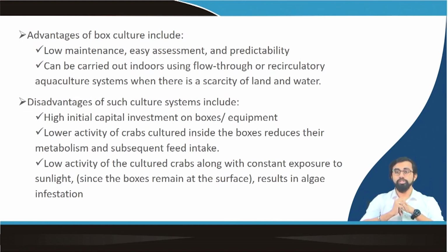You can utilize the flow through systems, or you can utilize some additional biofilter to treat the water and put it back again. That is what we call the recirculatory aquaculture system. That way you can utilize the water as much as possible, reduce the overall water demand of the system, and also reduce the environmental impact.